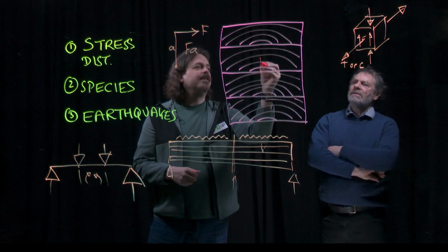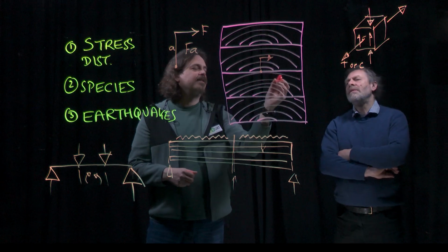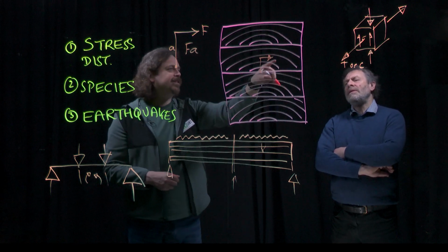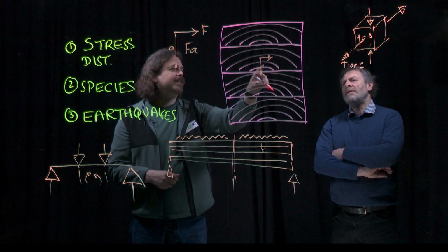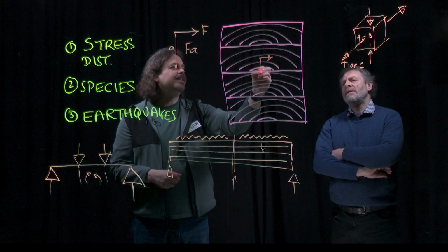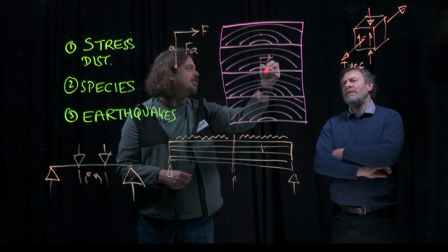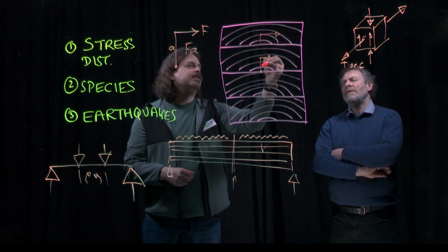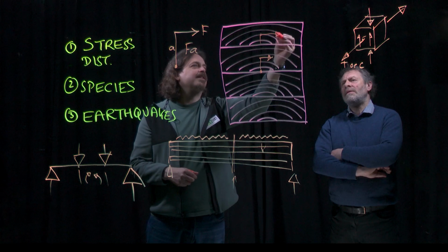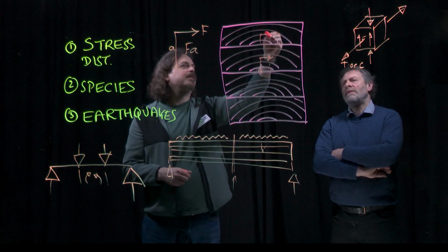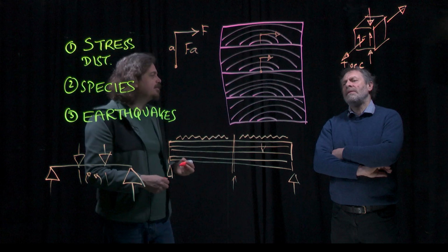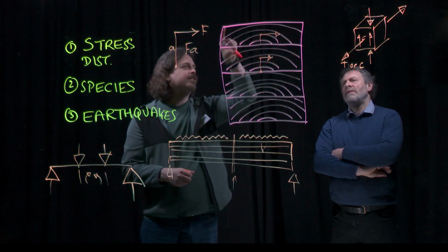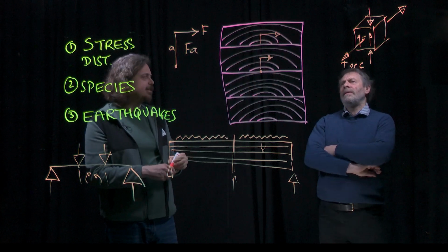And the force that's acting as the equivalent sum of all of the stresses in this lamella is acting at a small distance, and the force that's acting as the sum of all of the stresses in this lamella is acting at a longer distance. So it turns out there is more contribution to resisting the bending action in the top lamella. You end up with higher stresses.